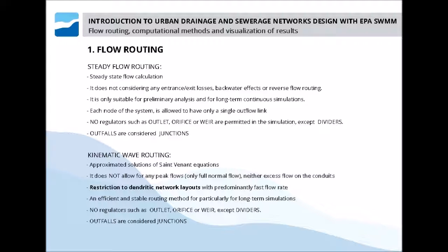This method is only efficient if our network is dendritic and there is no excess flow in the conduits. Therefore, we need to be sure of the layout and conditions of our network to make the right decision when choosing the kinematic wave method. If we're not sure whether the kinematic wave routing is a suitable method, we will choose the dynamic wave routing, described in the next slide.